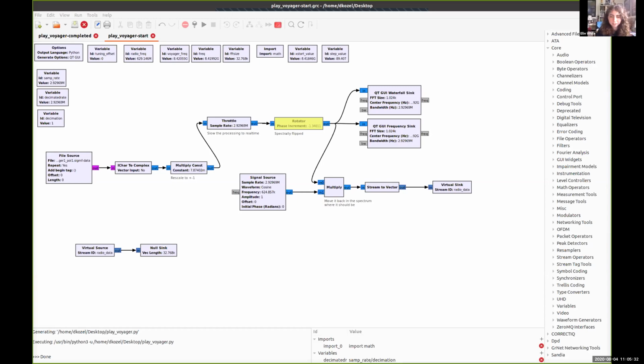Hey, Derek, I have a question if you don't mind. Go ahead. So what's the difference between the averaging that the frequency sync does versus integrating? Integrating is doing an addition operation on each bin. And so for each frequency index, it's just averaging all of the samples, or 100 of those samples together. The integrating, it's doing a straight addition.